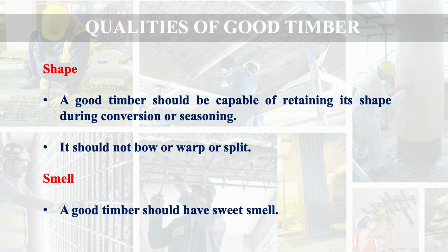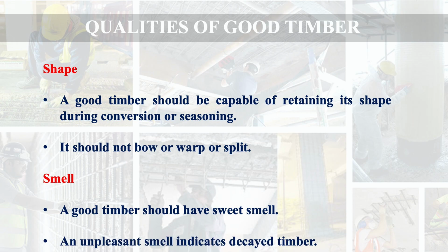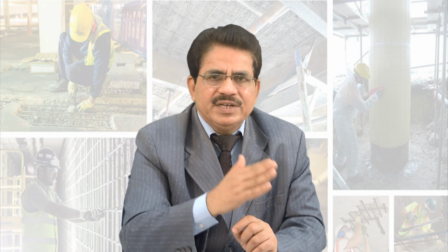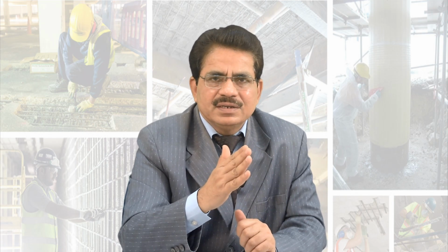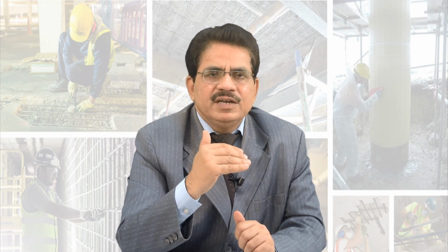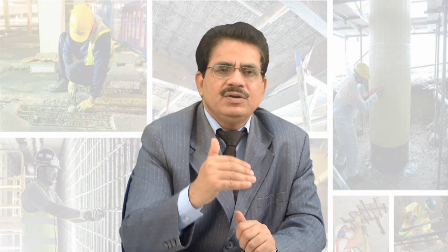Then next quality is smell. A good timber should have sweet smell. Why? Because an unpleasant smell indicates decayed timber. It is not about giving a good fragrance to the room, because the smell is linked with the health of the timber, and unpleasant smell means decayed timber. So that way a good timber should give sweet smell, not the unpleasant smell.